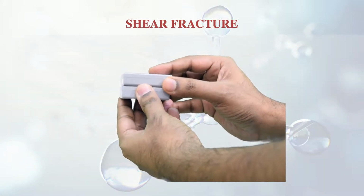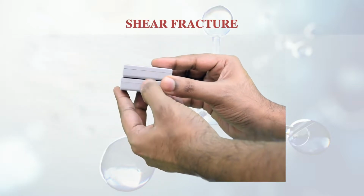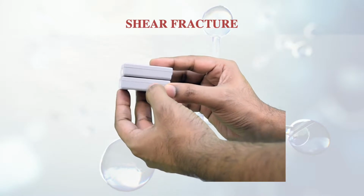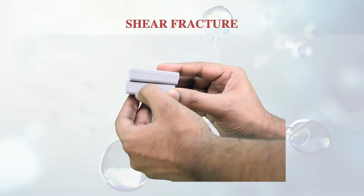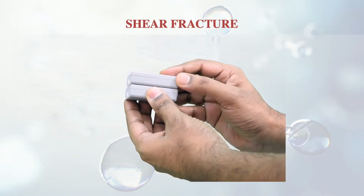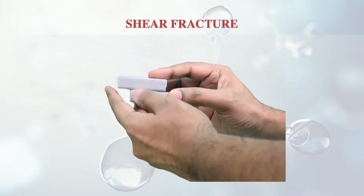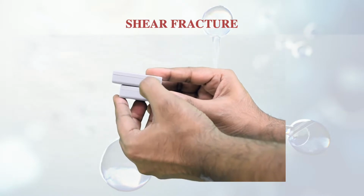Suppose this is the specimen, and these are certain layers, if you can see in the figure, of the particular specimen. Different layers are there, and if shear is taking place, slipping takes place, and only the middle planes of this particular specimen slip. Suppose here, this is one small plane up to this level and the other one is up to this level. If only these two are slipping, then the crack will be slanting type, because the upper portion is not moving completely. Whereas if the whole body slips, then what you can see here is that this will be completely perpendicular, vertical type. So the crack will not be slanting in that case.